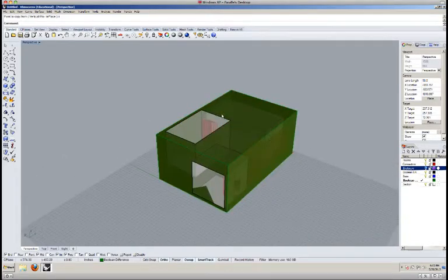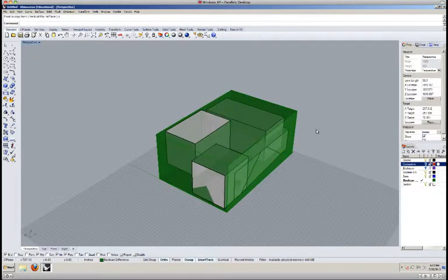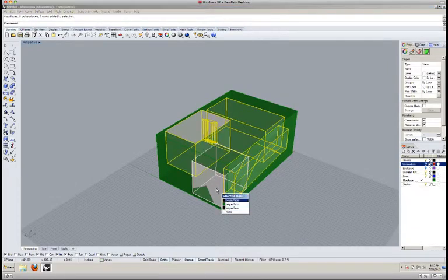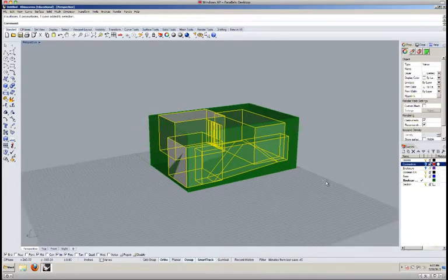I'm going to do the same thing by selecting all of these interior volumes, so everything other than the enclosure, and copy in place and put them on the Boolean union layer. I'm going to turn off my connectors. So now I have these guys, and the reason I did that was so that, again, I don't destroy the original objects. I want to be able to have these differenced out, but I want to be able to go back in and have those connectors joined together.